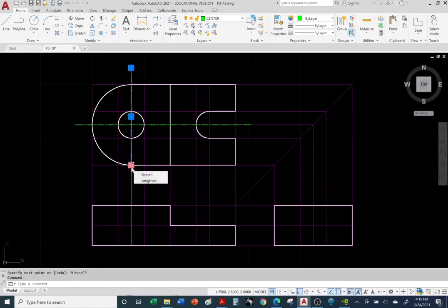So I'm going to left mouse click and slightly extend. It doesn't want to extend. Now the reason it doesn't want to extend is because it tries to snap back to any corner or midpoint. So I'm going to have to temporarily turn off object snap. Okay, so if you're having trouble locating that endpoint slightly extended, it's not going to where you want it to go, then you can turn off object snap. And you can now freely extend it, as you can see.